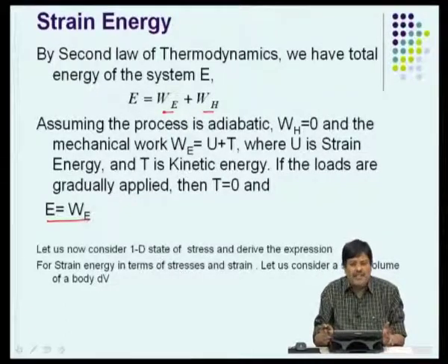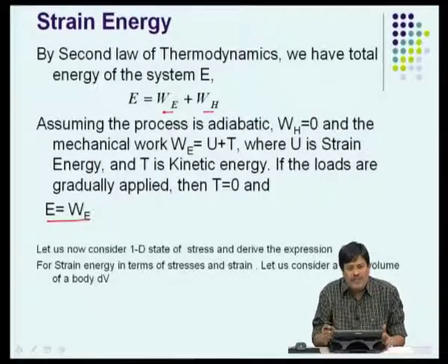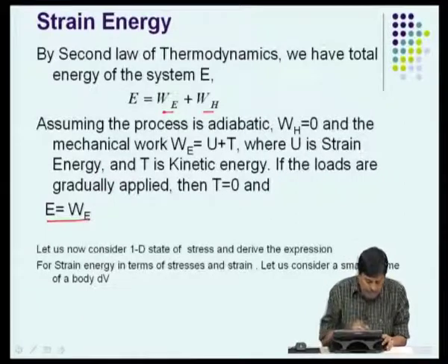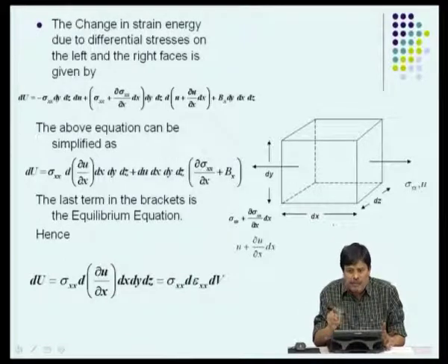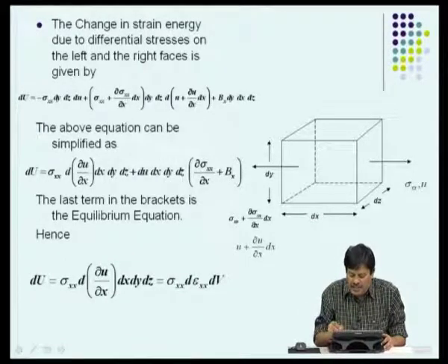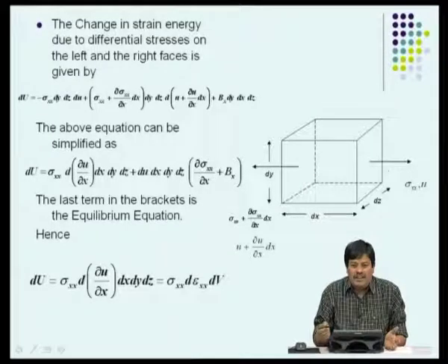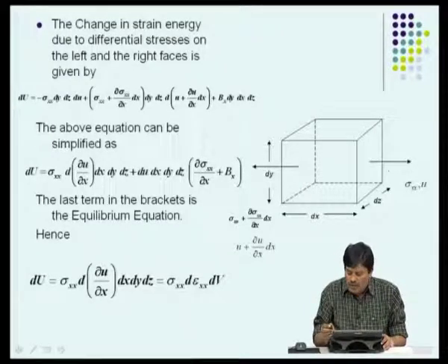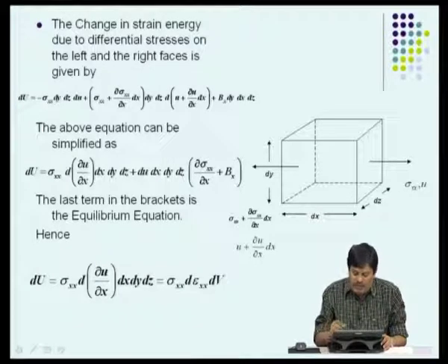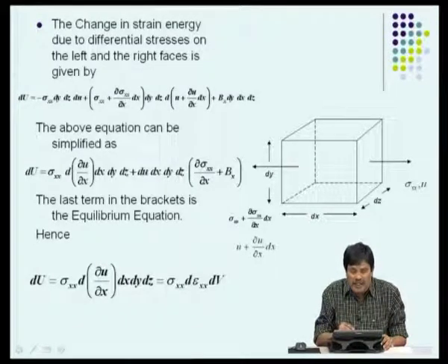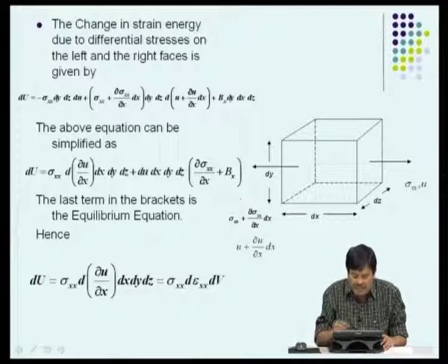Now, let us consider a 1D state of stress and try to relate this energy in terms of the stresses and the strains. Here we take a small representative volume of the body of length dx, dy and dz, and write the free body of the stresses. We have the stress on the right face sigma x, and the displacement is u, whereas on the left face we have an incremental change. So, this is not the same, it is changing by a small factor.